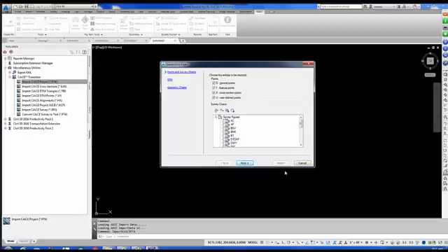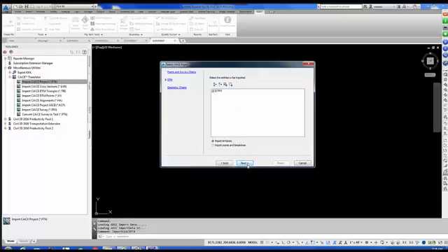Now, when we get in here, it says, okay, when you bring in the data, we're going to start out with points and survey chain. So right now, I've got all the entities to be imported under points. My ground points, my feature points, my cross-section points, my user-defined points. Okay? Now, if I select on this icon here, it would pick all the survey figures. When you use this, it would bring in those survey chains like it did in the TOPRD file, with the exception it doesn't put them on the right layers with the right colors. I believe they all come in on layer 0. For this example, we're not going to bring in the chains, but you could bring them in. So I'm going to uncheck that. So I'm just going to bring in the points. I'm going to hit next.